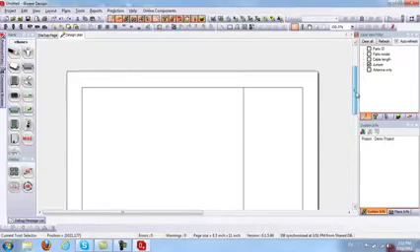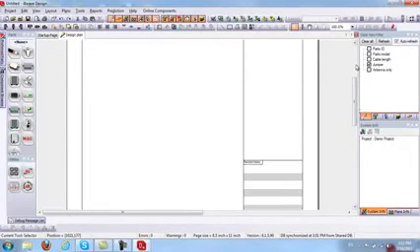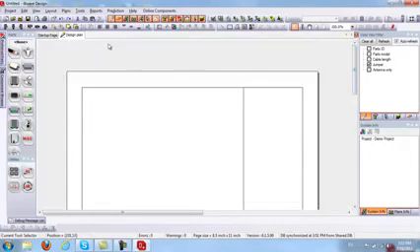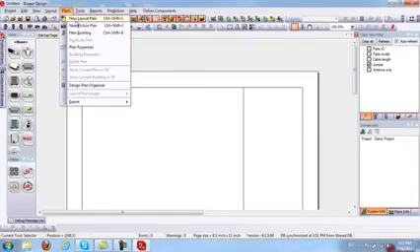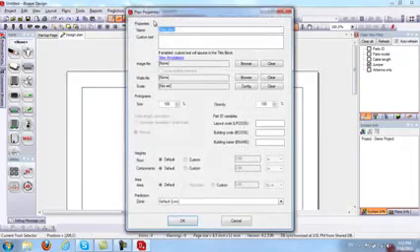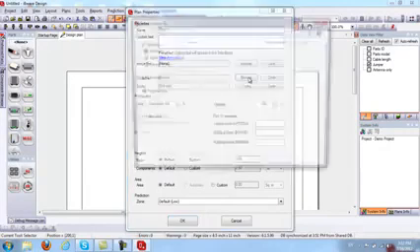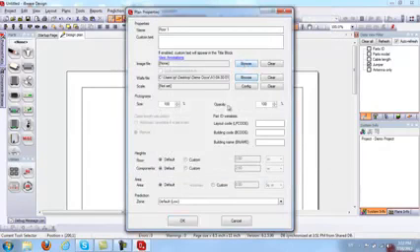Here you can start designing directly on your design plan page, or you can add floor plans or layout plans. I will go ahead and add a layout plan. I'm going to go to Plans, New Layout Plan, and it will give me a chance here to enter my floor name. So I'm going to put floor 1. Under Image File, this is where you can actually upload your image or PDF file. Under Walls File, this is where you can actually upload your AutoCAD file. So we'll go ahead and click on the Walls file and upload an AutoCAD file.